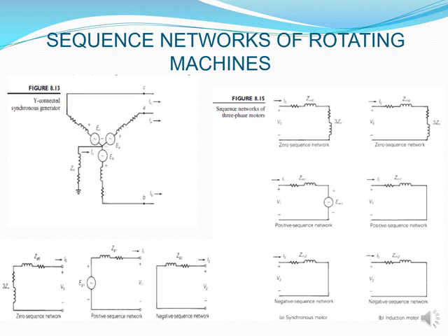I just want you to note that in both cases, be it a generator or a motor, when we're talking about the zero sequence network, you must always remember the 3 multiplied by your ground resistance or ground impedance that you are going to have, okay, whereas all of the others take exactly what was on your impedance.